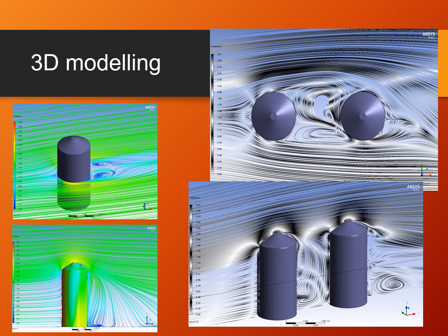In the interest of time, it is advisable in the first instance to perform a computation of a simplified two-dimensional model of a silo or a silo park. This would enable a tentative assessment of the design pressure on the body and conical roof of the silo in the park and subsequent generating of three-dimensional laws based on the result of the 2D calculation.